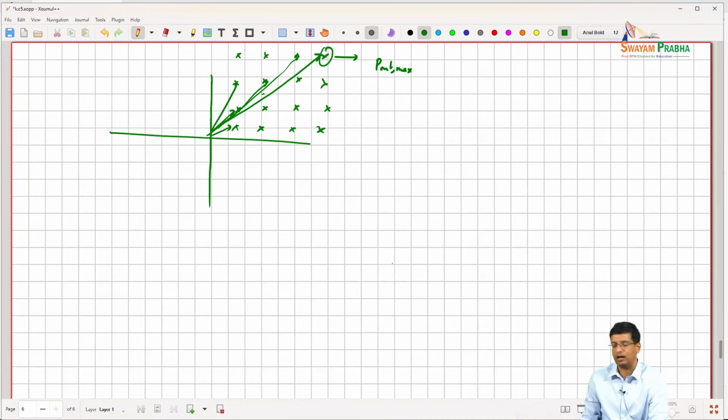So I have to design my PA so that maybe this is the saturated power of the PA, and then the PA is operating most of the time at a lower power than saturated because it's generating smaller amplitude signals. If I don't do this, then this signal will get what we call clipped, because the PA can't generate this power. So even for this constellation point, it will only generate this length of vector. So that becomes a problem.